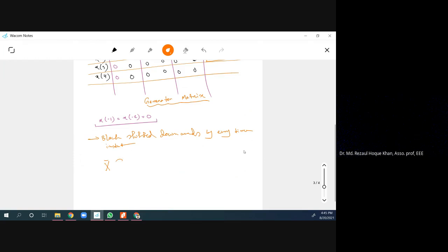This is our generator matrix G, which we generated just now, and it is equivalent to the code, which is our C vector. We found from here that anytime you pass your information sequence or vector through this generator matrix, we will end up generating your code.